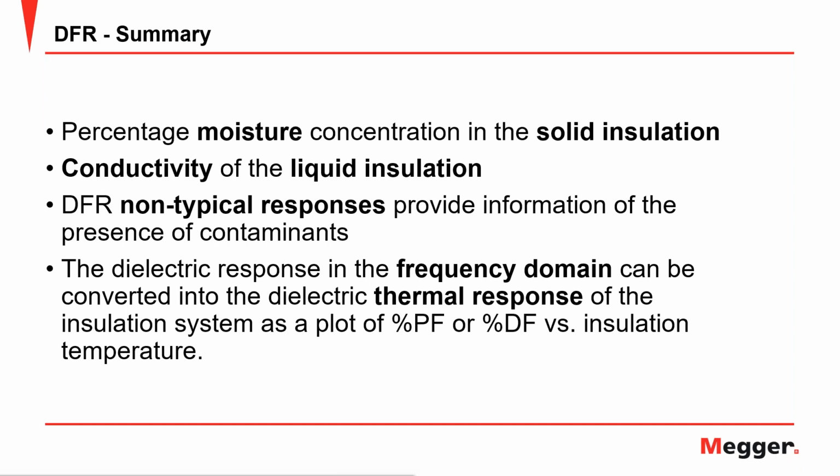And again, from frequency domain, we can go into the thermal domain, right, into the thermal response, and look at the power factor as a function of temperature. And that is a unique feature that we provide. So you can see that there's no table that will really correspond to what the insulation condition is at the moment that you are testing. And the other thing, something that Sanket was showing on some of the secret values, they are showing numbers for different frequencies, which are limits valid only at 20 degrees C.